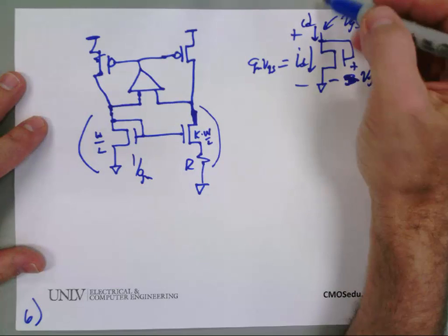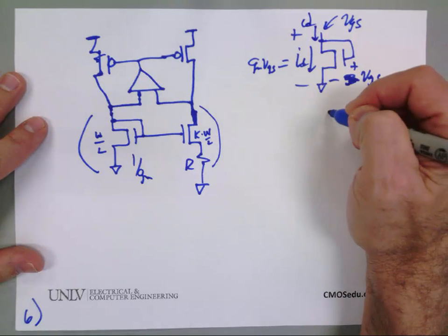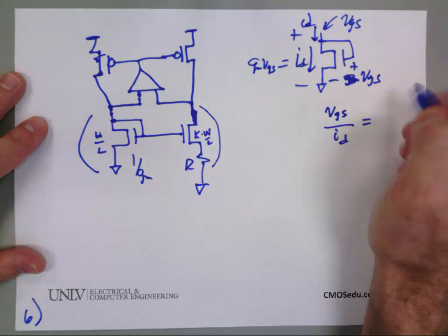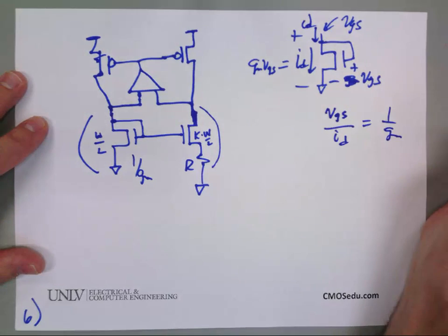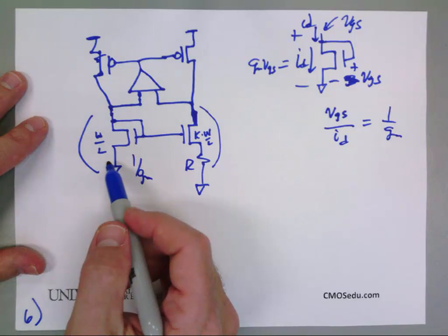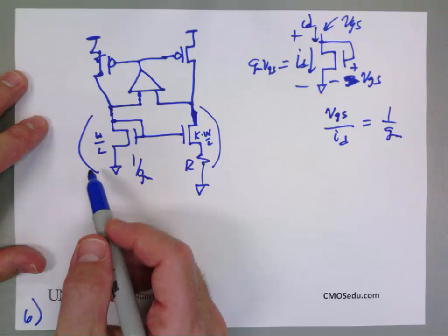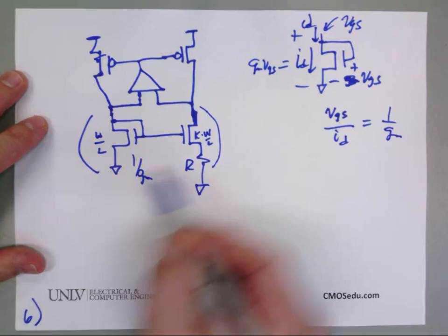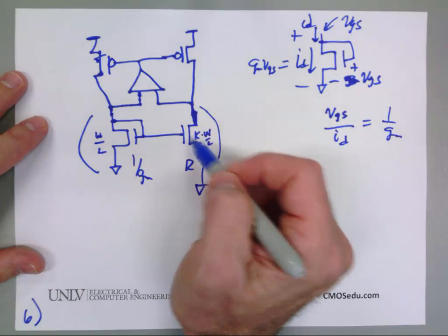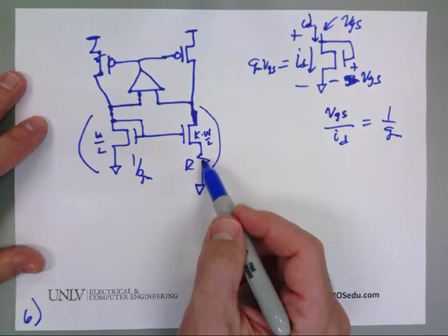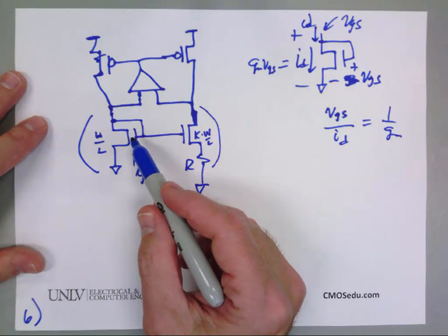So what's the impedance of the device? That's how I know that this is 1 over GM. Does everybody agree with that? So if this isn't a triode, it's going to have a much larger impedance than this, but at the bare minimum, this resistance and this resistance are the same if 1 over GM is R.